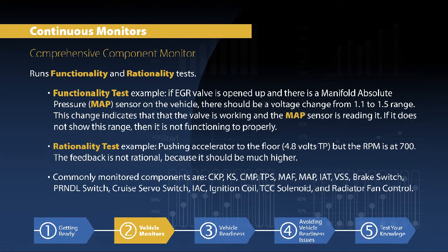The Comprehensive Component Monitor, CCM, is an onboard strategy designed to monitor a failure in any electronic component or circuit that provides input or output signal to the powertrain control module, or PCM. It is not exclusively monitored by another system. Inputs and outputs are considered inoperative when a failure exists due to an open circuit, out of range value, or a failed rationality check. The components monitored may belong to the engine, ignition, transmission, air conditioning, or any other PCM-supported subsystem.